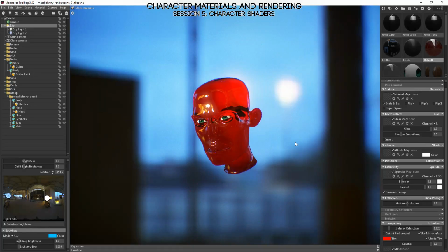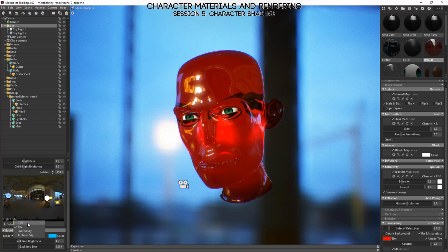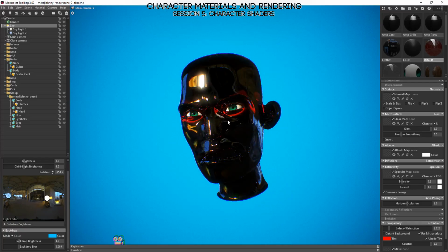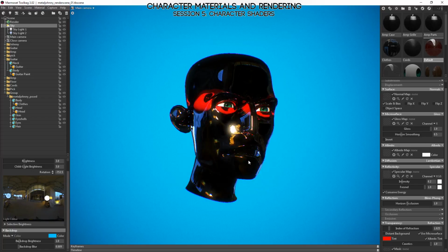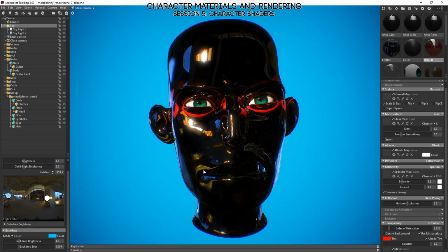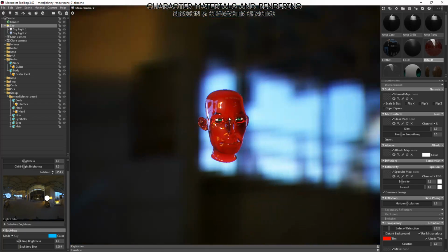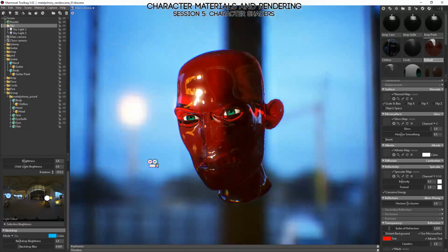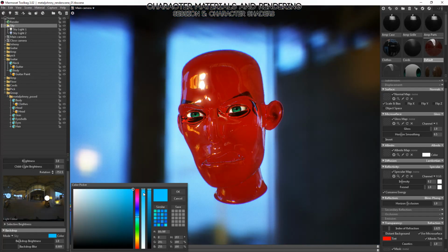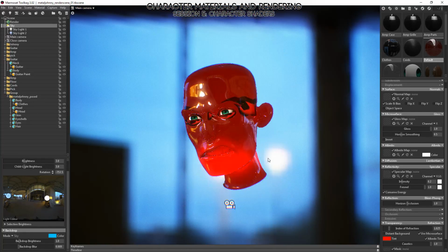And you'll notice that if I have just a flat color in the sky, we're not actually getting anything coming through here. All we're seeing is a little bit of the eyes in there. Now, this is one example of a limitation of screen space effects. It doesn't take into account just the color that we have plugged into here. It could be for any number of reasons. However, if we turn the sky on, now you can see that it's refracting the sky. Once again, that could be an oversight in the way that the shader was written. It could be a technical reason behind how the color is displayed. But once again, that's an example of how limited screen space effects can be.